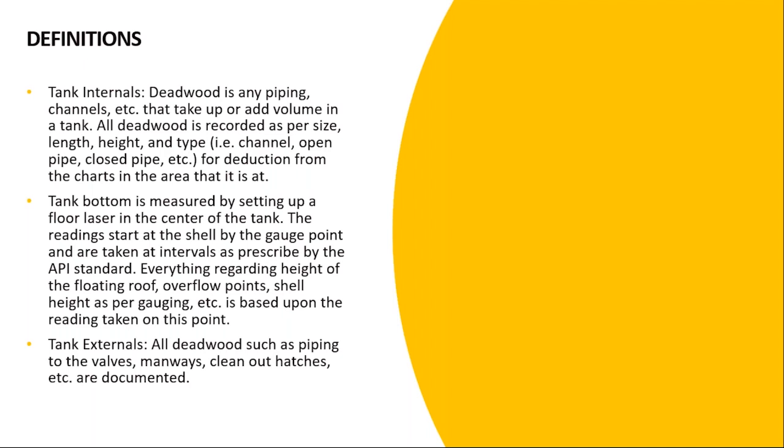Or what we sometimes use is what we call combined method, and we use volumetric measurement of the bottom of the tank, and then we do geometric for the rest of the cylinder. Okay, and that is going to provide us with some reference points to accurately correlate level to volume, and also it's going to add up to our total actual volume of the tank.